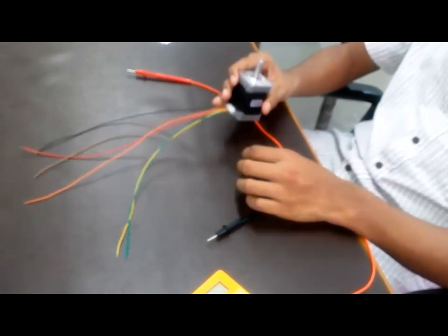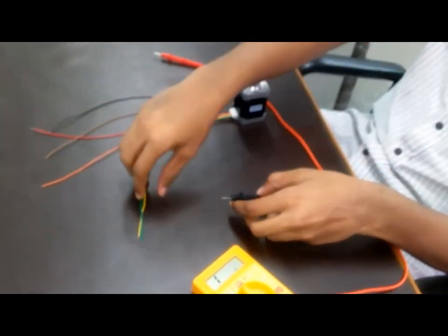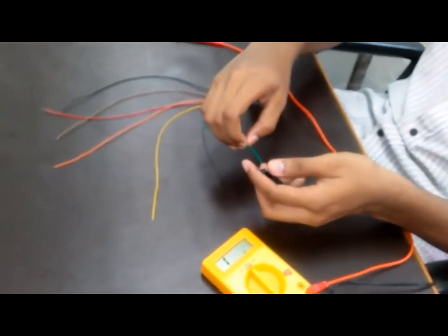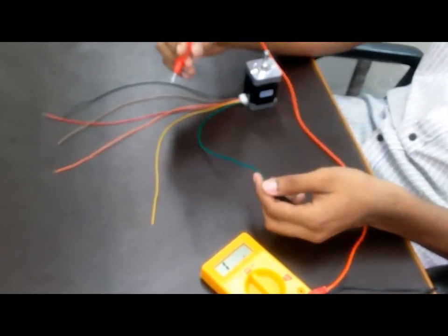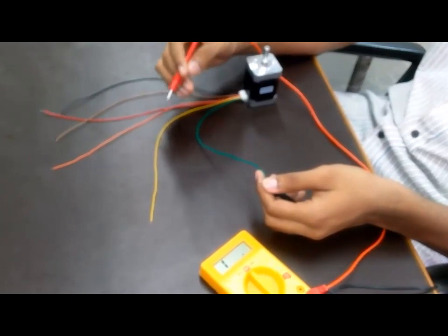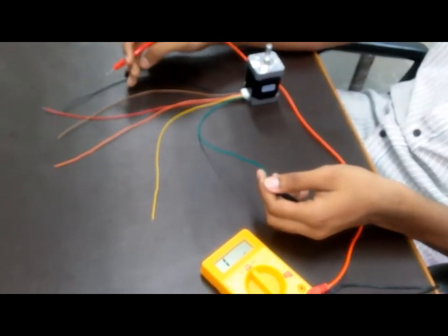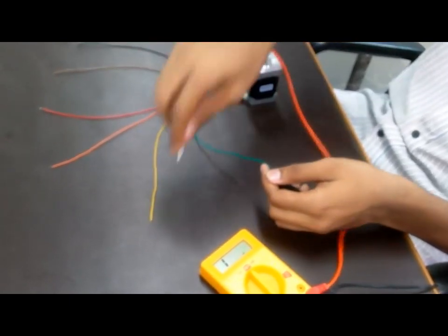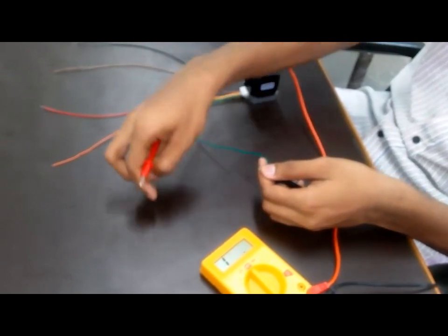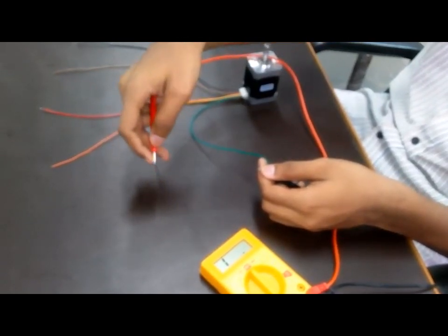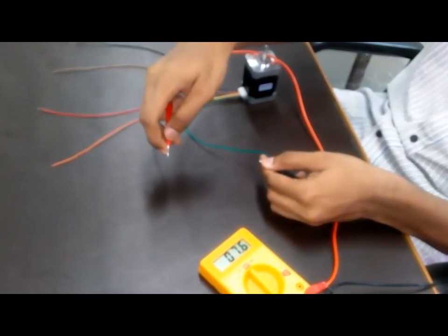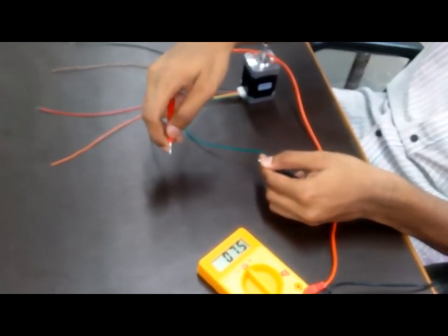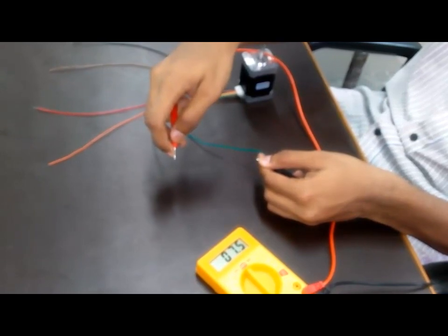This one is a 6-wire unipolar stepper motor and has two common wires. To identify them, connect one wire to one leg of the multimeter and serially try to check the resistances with each one of them. The second wire shows a resistance of 7.5 ohms.